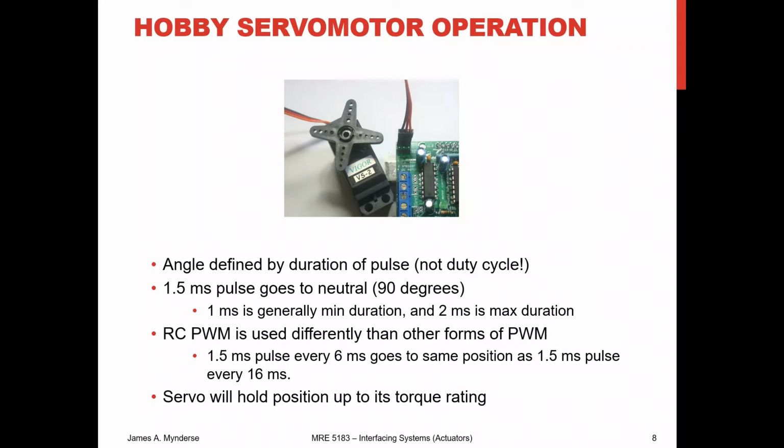Also, a nitpicky sort of personal complaint is that when I think about servo motors, I think of somebody having done the controller design for you already. So remember, they are position control, not speed control. So you get whatever response characteristics the designer chose. If you want a particular response rate, you got to buy one that has that response rate.